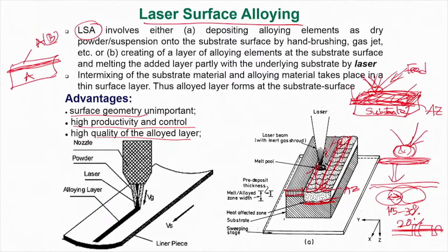Now in order to protect the powder feed or wire feed or whatever we are delivering, we also would like to ensure that there is no undue oxidation. At the delivery point, the beam temperature could be anything from several hundred degrees, like 500 to 2000 or even higher, depending on what parameters we choose. Of course we can control that. The entire heat transfer is purely dependent upon the parameters we choose. But the point here is that when we expose this zone, which is a melt pool, we are feeding powder into that melt pool.